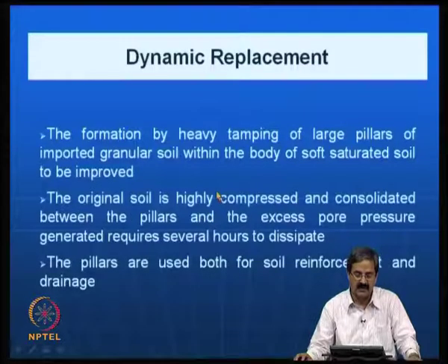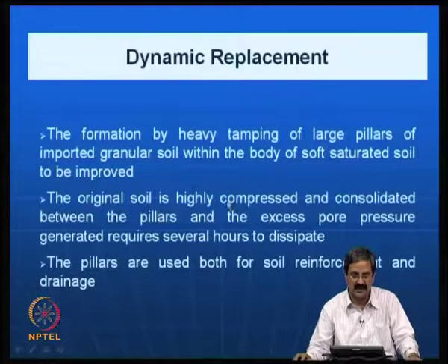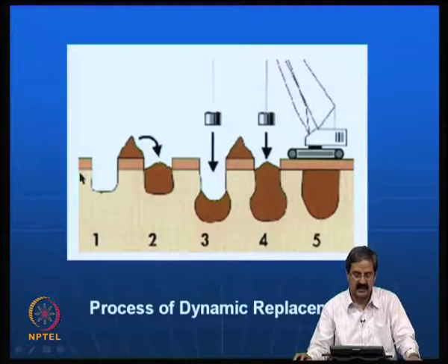There is another one called dynamic replacement, in which you have heavy tamping of large pillars of imported granular soil within the body of the saturated soil. So the original soil is highly compressed and consolidated between the pillars, and the excess pore pressures generated require several hours to dissipate. Pillars are used both for soil reinforcement and drainage, like this here. You just excavate, and it is actually what we call dynamic replacement.